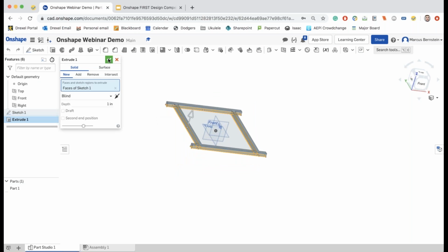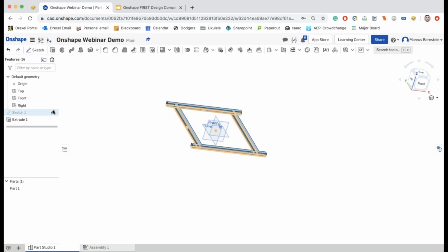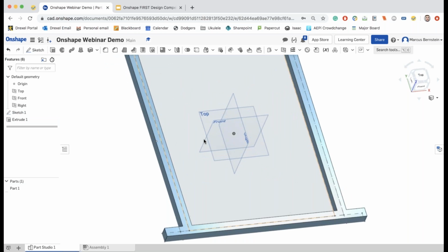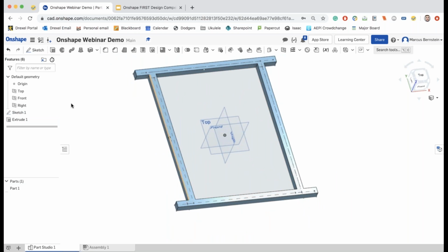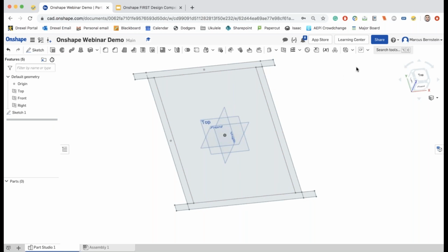As you can see here, if I do a simple extrude based on this sketch, it's clear from the top view that I wanted 2 cross members and 2 drive rails. With the original Onshape tool, because of the logic that exists, it's going to make it all one specific part. What I'm going to do now is demo how to pull FeatureScripts into your Onshape document. And then once those are in, I'm going to demo the first one, extrude individual.